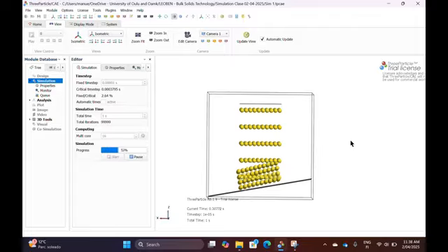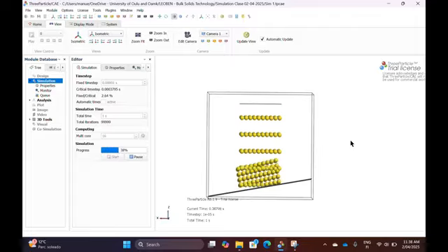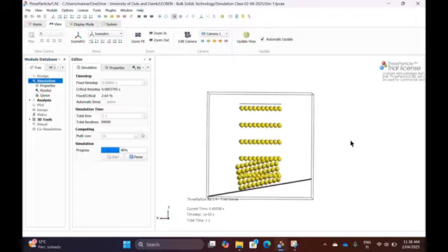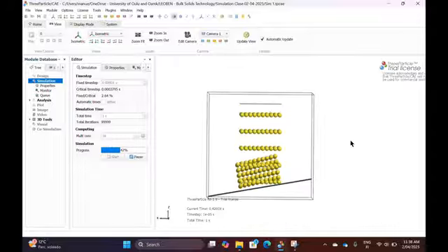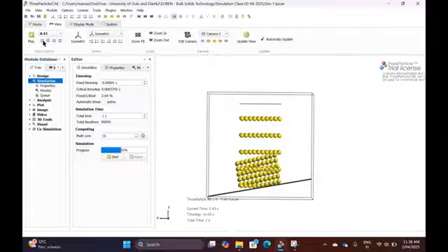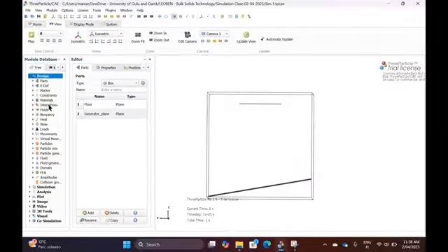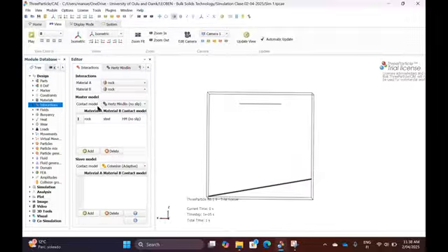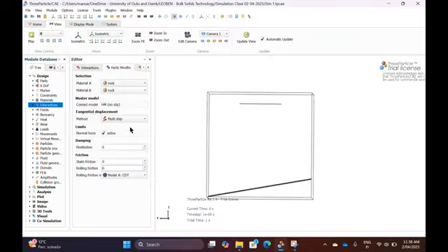Because we didn't define interactions between the same particles. Same thing as before. Absolutely right. So we can go back to interactions, and we define rock to rock. Similar as before, but I want to have stone to stone with even a little bit more damping, like 0.1 or even below. Rocks do not behave like steel balls. Rocks are more damping. 0.1, and static friction I choose just the same, so I have starting values. Again, save, and I start the simulation.